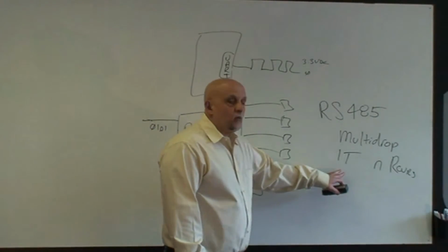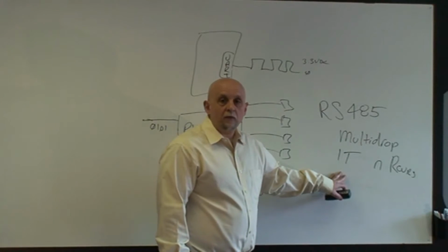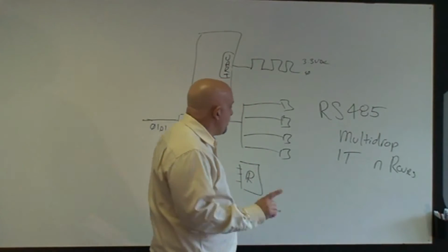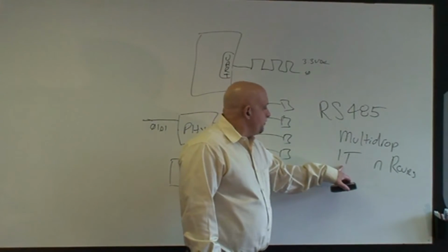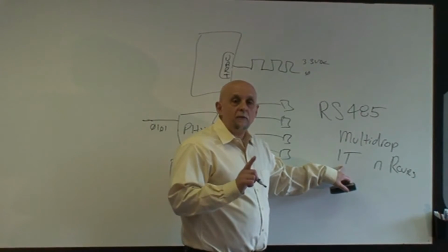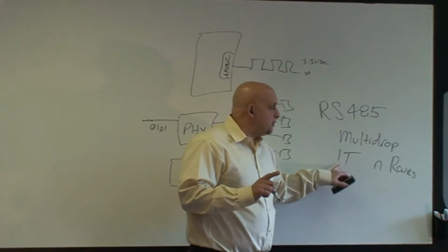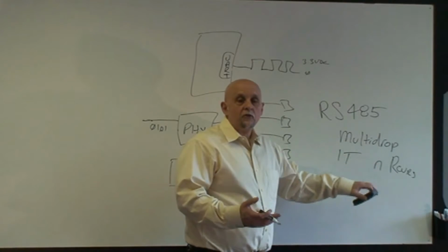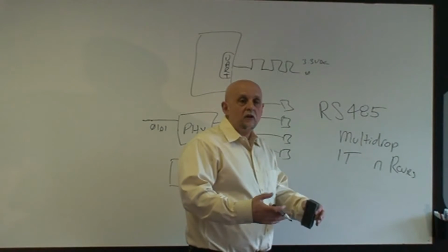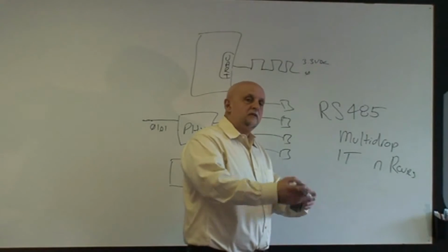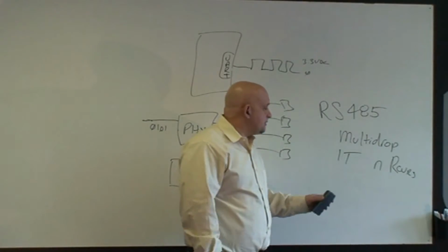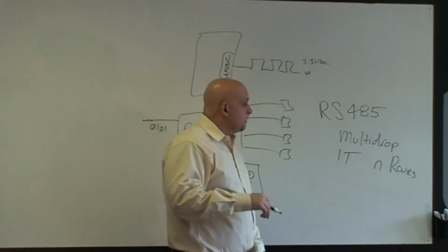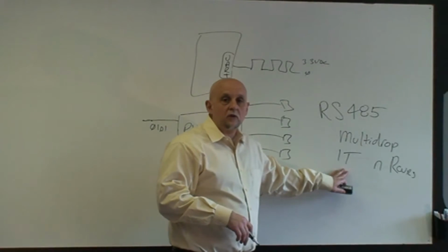This is what's called half duplex transmission. Half duplex because you only have one communication going out at a time. The transmitter sends something out. All the receivers are listening. The receiver then gets a message. He becomes a transmitter, sends something out while everybody else is listening, including the old transmitter. So this is half duplex communications.